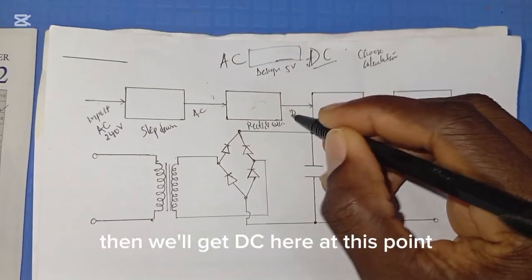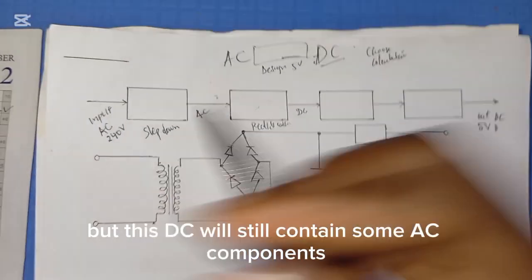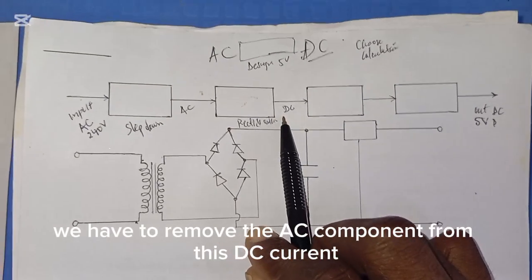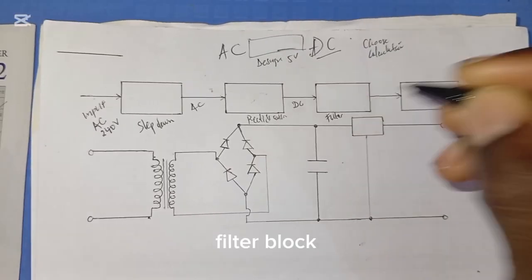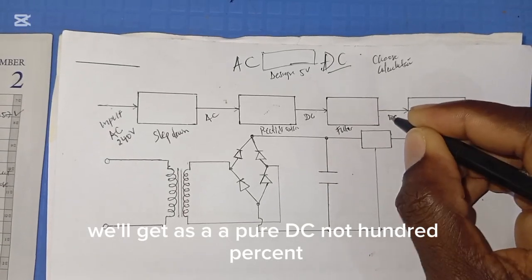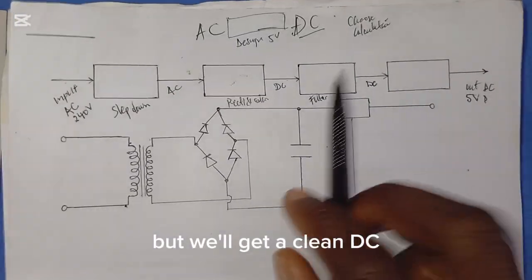Then we'll get DC at this point, but this DC will still contain some AC components. Then we'll have to smoothen it. We have to remove the AC components from this DC current by filtering, so we'll have a filter block. After filtering, we'll get a clean DC, not 100% pure, but a clean DC.